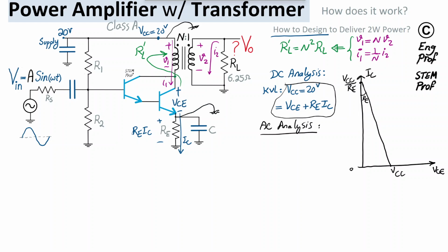So the two AC voltage drops: one is V1 AC across the primary of the transformer, with the polarity that is shown, plus minus, and the VCE AC. The sum of these two should be 0 because they are between two AC-wise ground nodes. So I can write V1 plus VCE AC of the Darlington BJT transistor should be equal to 0.